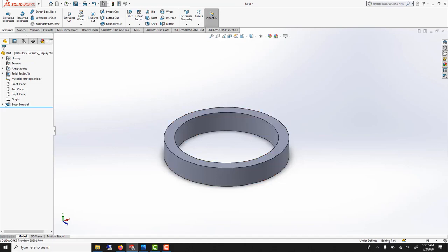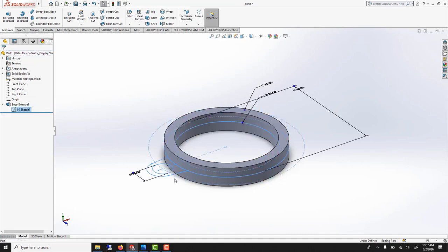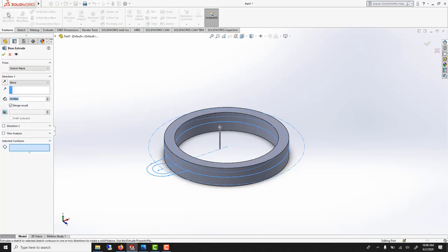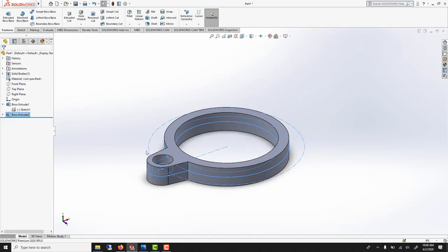And the reason I'm doing this is that I'll be able to extrude this one. So I select the sketch, extrude, and this time you can pick this one. So the result is the same, they'll merge, but you could just repeat the one you need. So mid-plane and the same 10 inches. So this is the selected contour function.